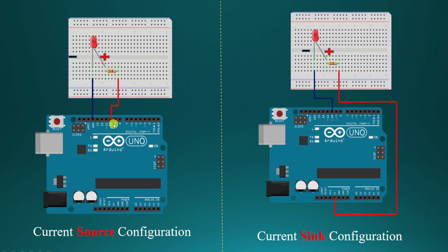So in that case, the LED pin will act as the source of the supply voltage to the respective LED, as the negative pin of the LED is connected to ground. In that case, the current consumption of the respective controller will increase, which may damage the controller or overload it.